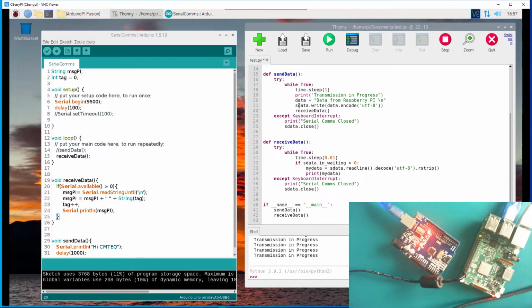Because we are now writing into the serial port sent to the Arduino, and we are also going to receive just after writing. But we need to pause for a fraction of a second after writing. That's what we're doing here. And then we're going to check if there is indeed data in the waiting list so that we can do the reading. But before we do that, we need to change this condition in the while loop. Otherwise, we're going to be stuck in this while loop and we're no longer going to exit and do the write. So we'll only be reading.